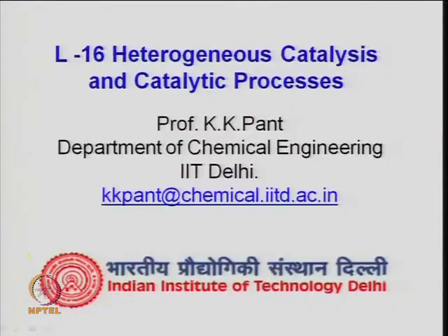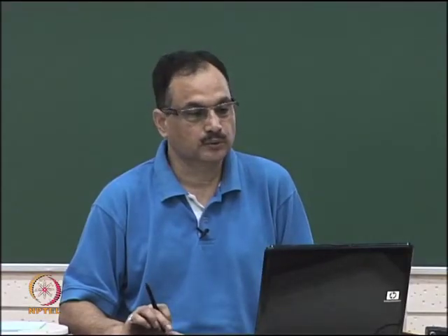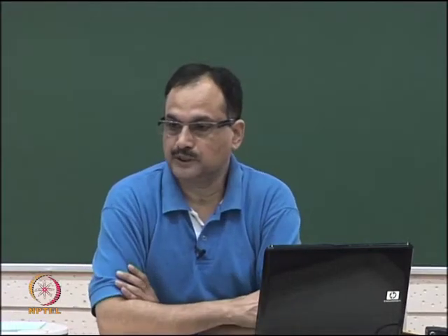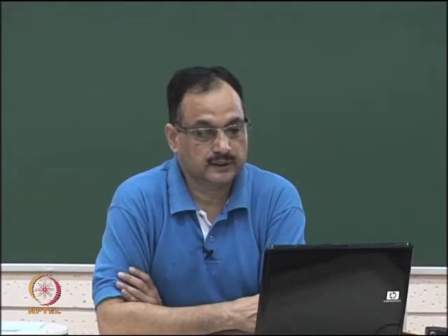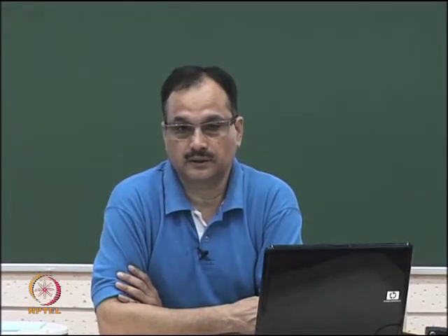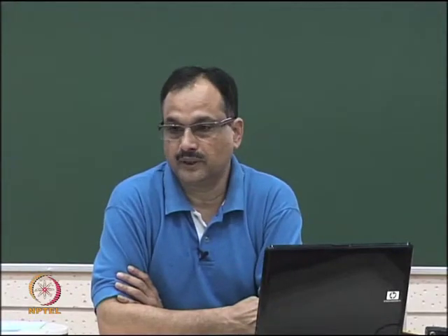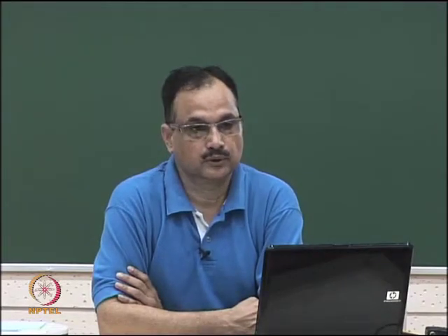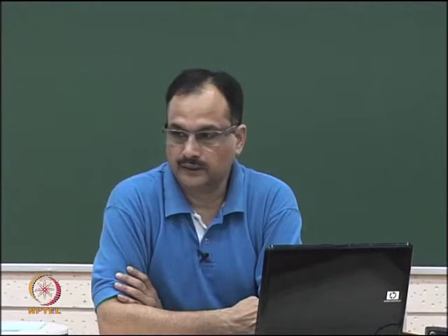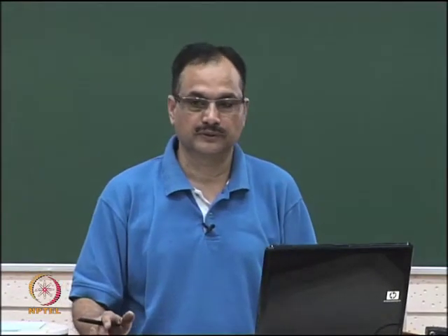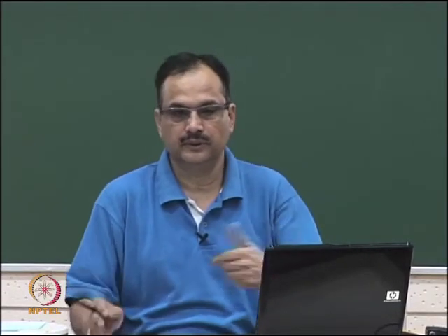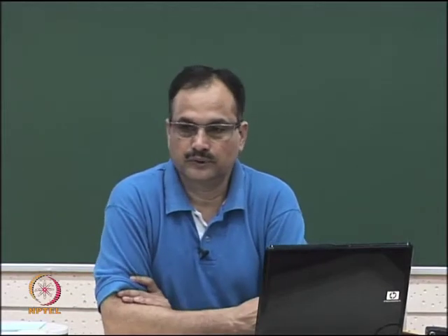Morning. Last time I was talking about transmission electron microscopy, and we were discussing the electron microscopy principle. It was discussed that depending upon the characteristics of the primary beam, which may have 400 kilo electron volt of energy and may start from 50 kilo electron volt, a high energy beam of electrons impinges on the surface, and it can be primary, secondary or back scattered electrons. The energy of these electrons which may diffract or transmit from the surface is measured.